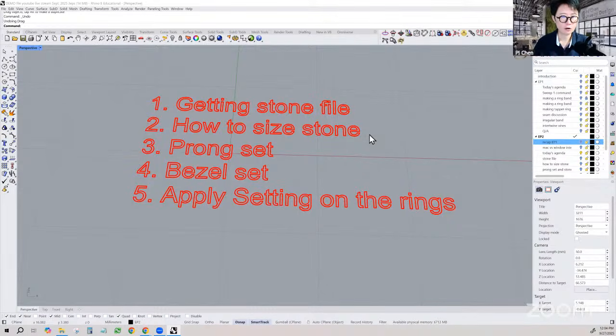When the metal comes out of the casting, it's more of a satin finish. So you need to polish, and when you polish, you lose material. When you lose material, things get thinner, right? So as a CAD designer, we need to calculate that back into our CAD, so we understand how much material will be wasted or polished off.